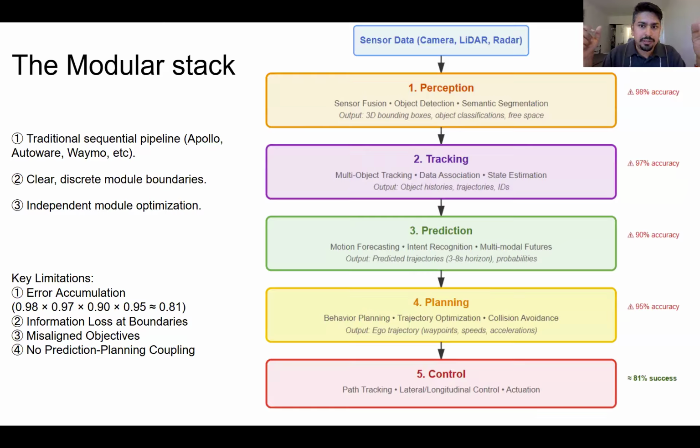The perception part has mostly been neural network driven. Most of them use a lot of neural networks on training data to come up with bounding boxes, as well as other things. Then there has been a class called tracking, which is essentially you have your raw data from the perception, the sensor fusion data.